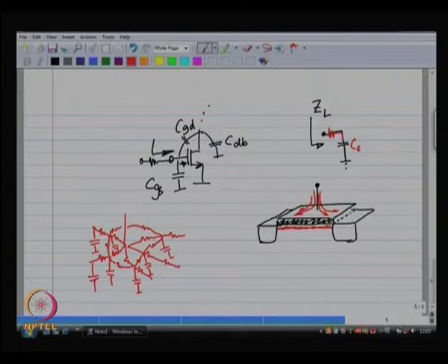where C is the capacitance of the gate to channel, COX or CGS or whatever you want over there, and RG is the gate resistance. So, this is the gate resistance that I am talking about. It is a distributed mesh of resistors all over the gate.